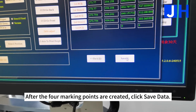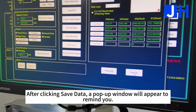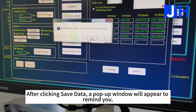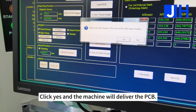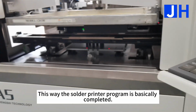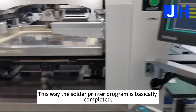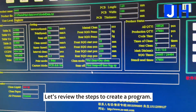After the four marking points are created, click Save Data. After clicking Save Data, a pop-up window will appear to remind you. Click Yes and the machine will deliver the PCB. This way the solder printer program is basically completed. Let's review the steps to create a program.